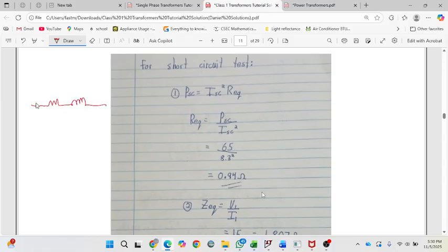this going on here. So you have here I1. Remember, for the short circuit, only under short circuit conditions, your input current is the same as your I1, because under high currents, your I no load is assumed to be negligible. Okay, so you have your REQ and a jXEQ. So it's in series. The open circuit is in parallel, so the calculation will change up a little bit.